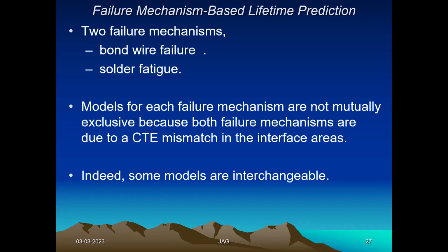remaining useful life prediction. I know it has already undergone, say, 50 degrees centigrade. It was operating for 1 hour at 50 degrees centigrade. So there will be a degradation, right? The reason for the degradation is the increase in temperature. So how much degradation will happen? That study I have to make. Then I can predict: it was supposed to operate at 40 degrees, it operated at 50 degrees for 1 hour, so this much degradation has occurred and it has this much more life. There is a possible failure after 1 month, whereas otherwise it would have happened after 1.5 months. So that is called physics of failure based lifetime prediction.